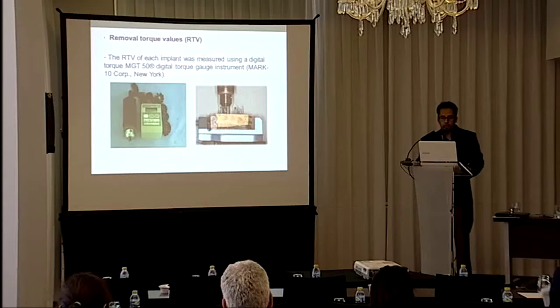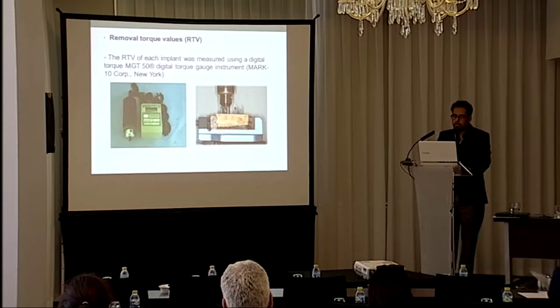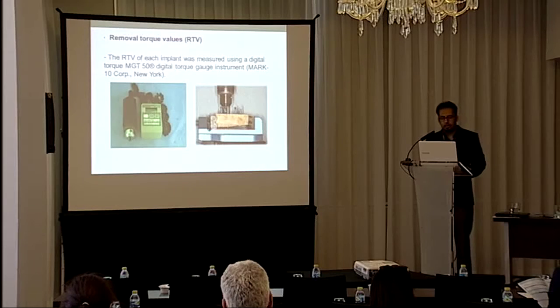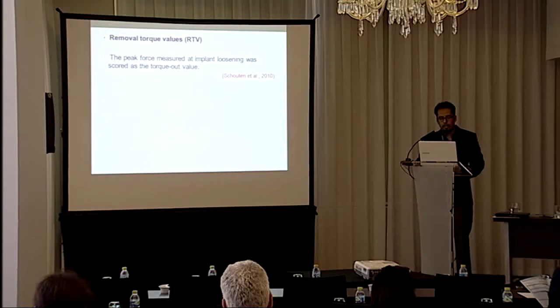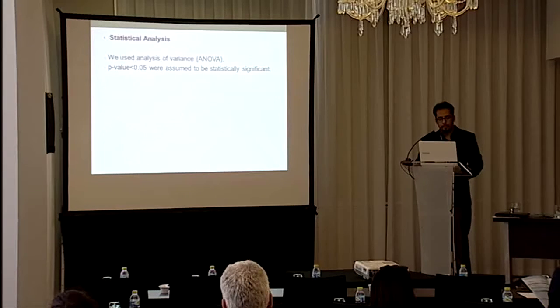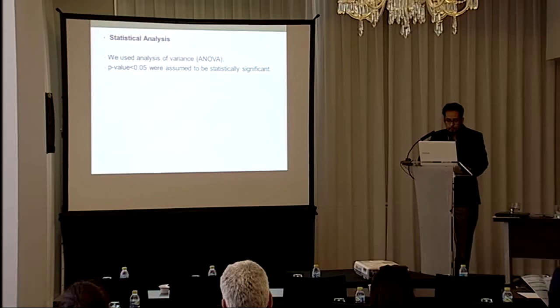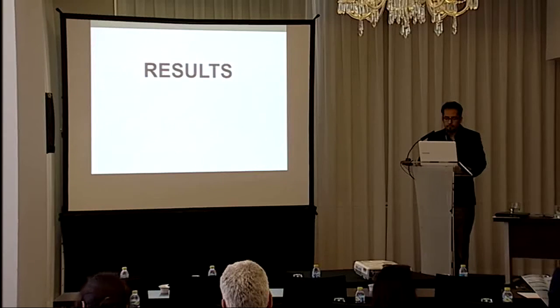The removal torque value of each implant was measured using an MGT 50 digital torque gauge instrument. The peak force measured at implant loosening was scored as the torque out value. We used analysis of variance, ANOVA. P-values less than 0.05 were assumed to be statistically significant.